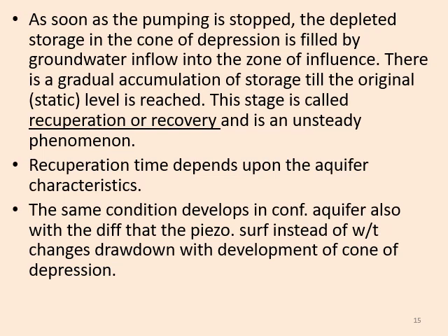In this condition, naturally, groundwater will flow into that particular area from where we have pumped out the water. Accumulation of storage will happen until the original water level is reached. This stage is named as recuperation or recovery of water table, and it is an unsteady phenomenon. The time required for recuperation or recovery will depend upon the aquifer characteristics.